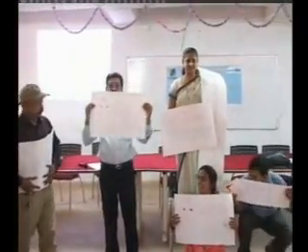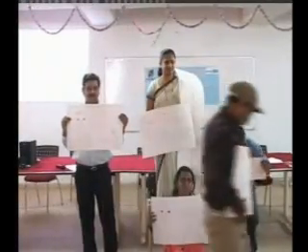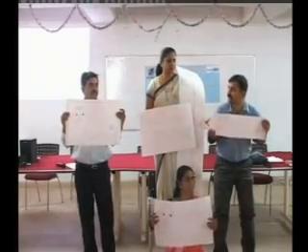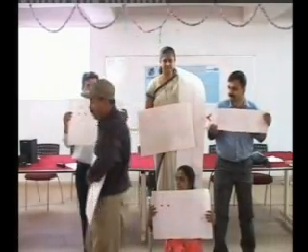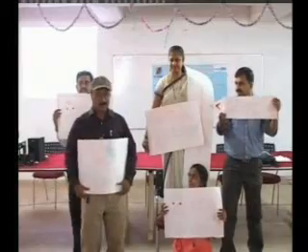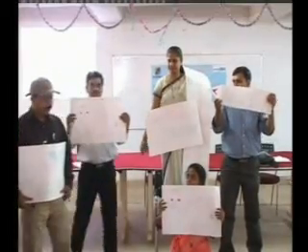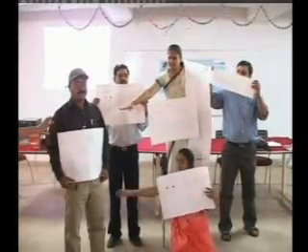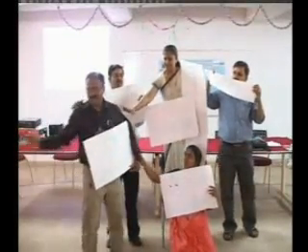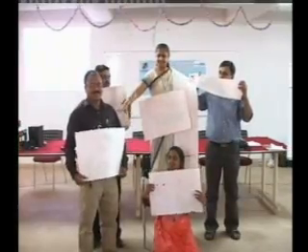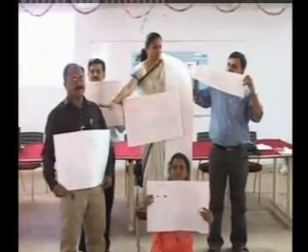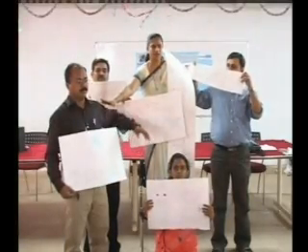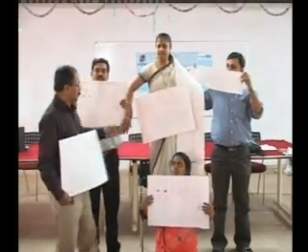The water is coming in at the rate of 5 liters per minute and going out at 2 liters per minute. We have a controller in addition to the other scene. What happens is, in the smart tank there is a sensor probe which is detecting the lower level as well as the upper level. Now the upper limit has been detected, that the tank is full. I've got a signal, I'm giving it to the controller.